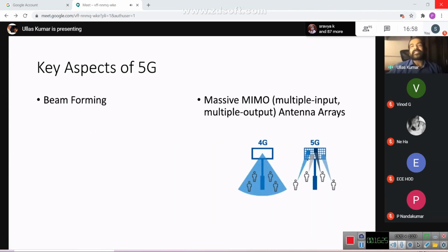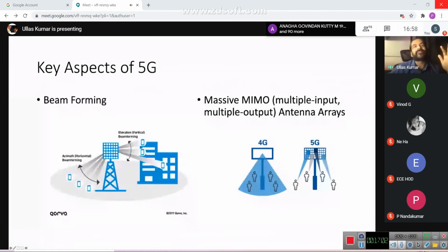The other key aspect is something called massive MIMO. So rather than having a single element of array, now you have a significantly higher number, 64, 128, or 256 elements of arrays, so that you can address individual users with those individual arrays, with a technology called beamforming. It becomes efficient to manage individual customers. Rather than whitewashing everybody with the same signal, you give people what they want. So we can limit it that way.